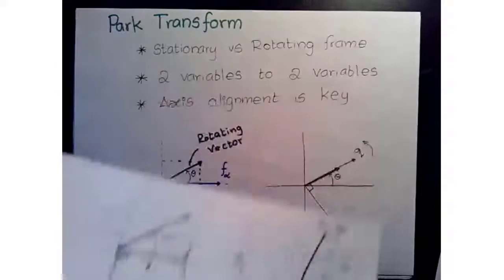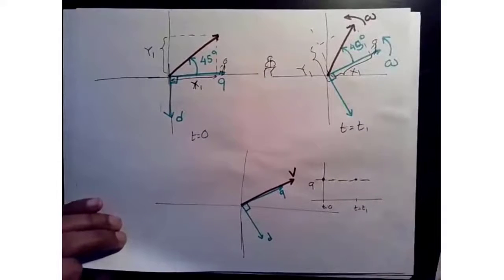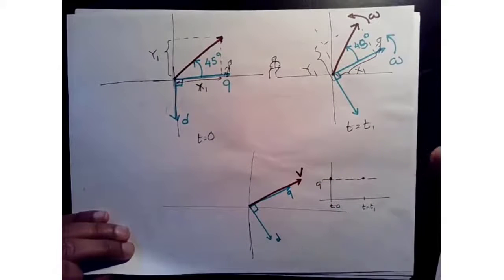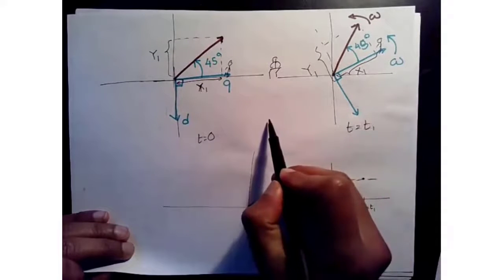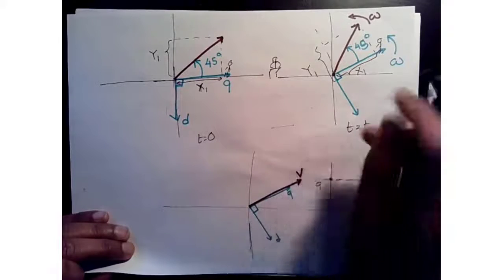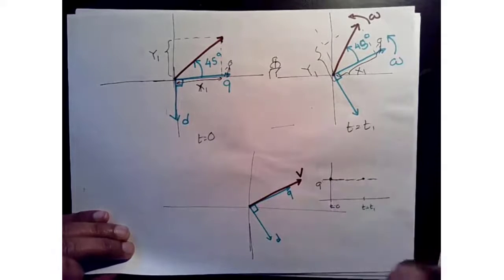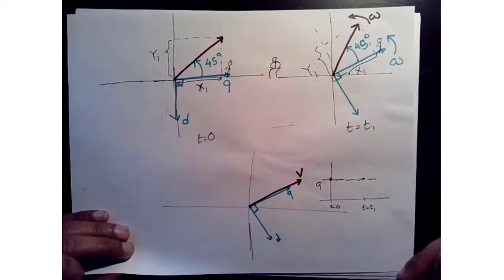Why is that helpful then? Exactly. You're not going to see the value just yet. You will see the value when we go into synchronous machine analysis, because we can now convert our AC currents to look like DC currents using this transformation. And now your controller can treat your motor as a DC motor or a first order plant rather than an AC signal.